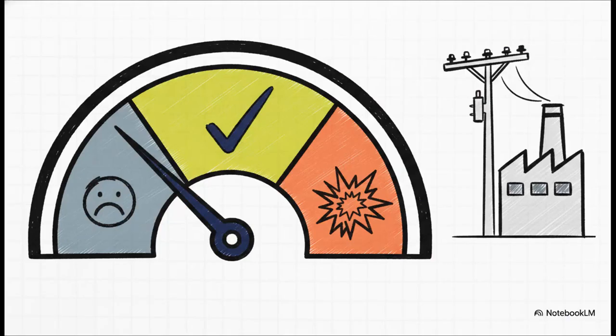Right, so here's the really crucial point when you actually step onto a job site. You've got to know the rules the utilities enforce. See, most utilities will absolutely hammer industrial customers with heavy demand charge surcharges if your power factor drops below 0.85. They want you operating efficiently, for sure. Because of this, substation design usually targets correcting to somewhere between 0.95 and 0.98 lagging.